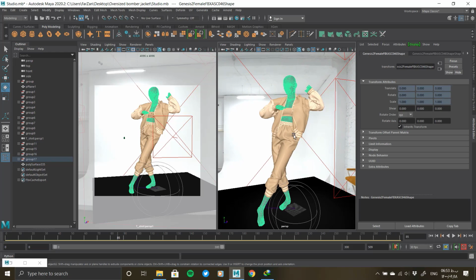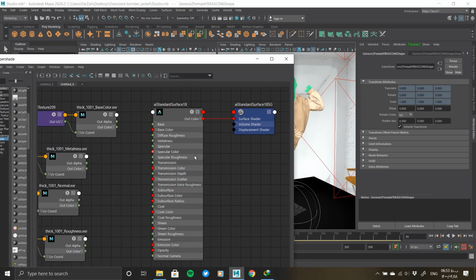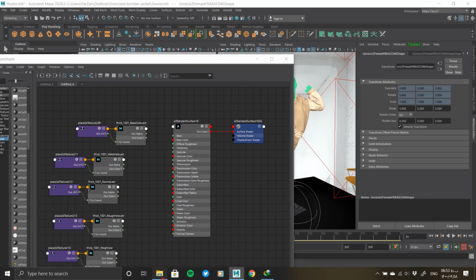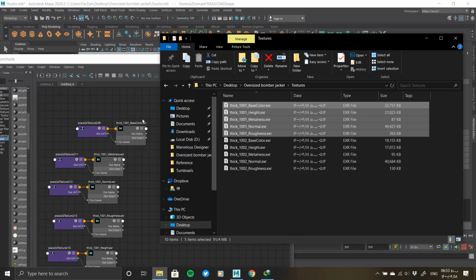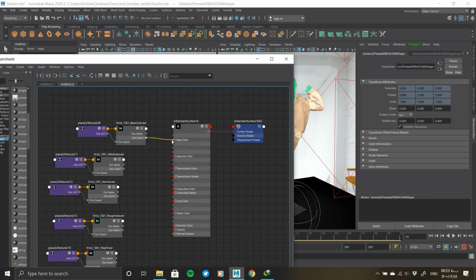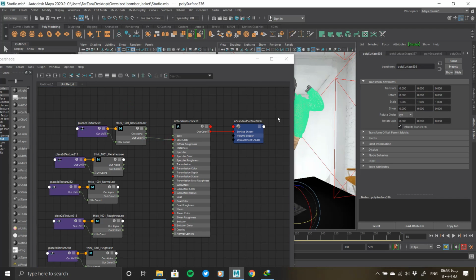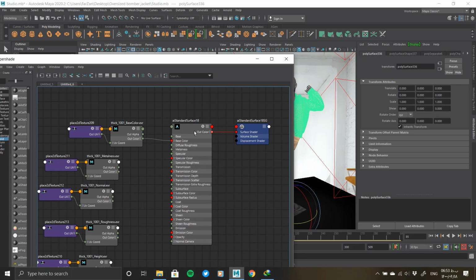We enter Maya and enter the low poly model into the studio. And after placing the camera and adjusting the lights, we start importing textures, and in the Hypershade, by creating an aiStandard surface, we start connecting textures to each of our parts. Different nodes may be used, including BUMP2D, Displacement Shader, Divide. Then we attribute the made material to the model.